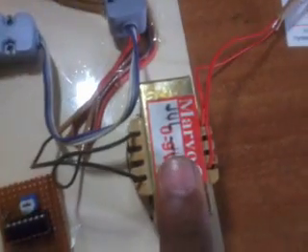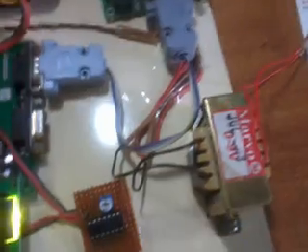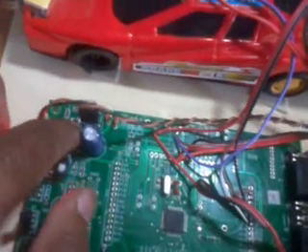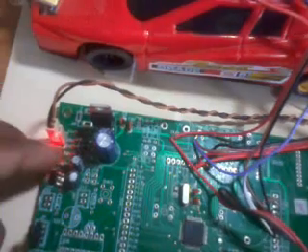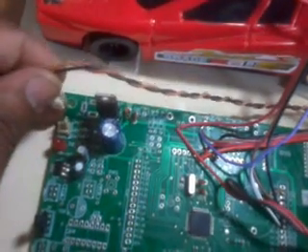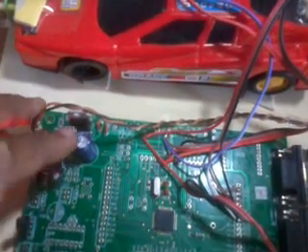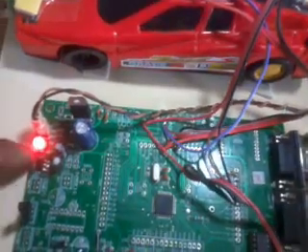We are using a 230 volt input and a step down transformer, with 9 volts AC output at 1 amp. Here we have a bridge rectifier, filter capacitor and the 7805 regulator. This LED indicates whether the power is coming properly or not. When I insert the AC, it converts AC to pulsated DC, eliminates the ripple and converts it to 5 volts, and the LED displays that the proper power supply is coming.